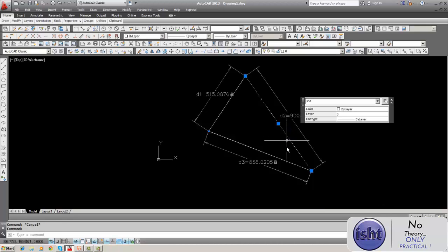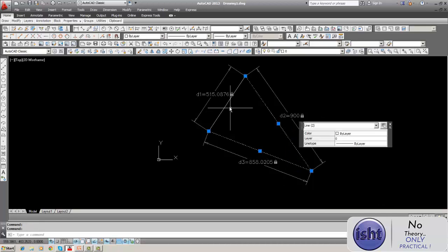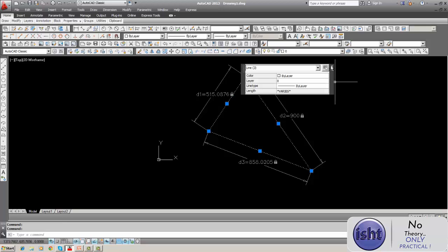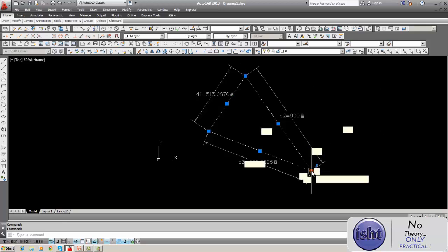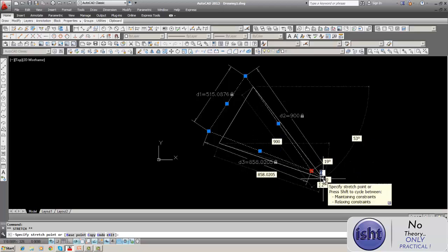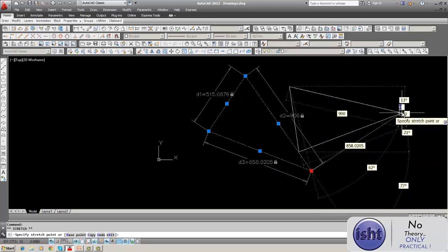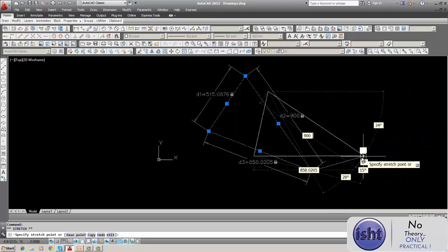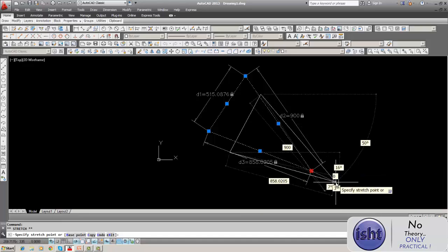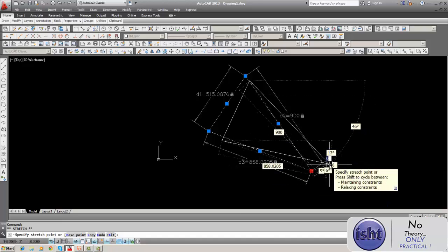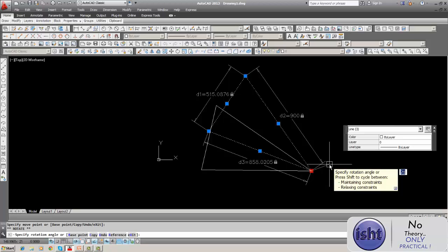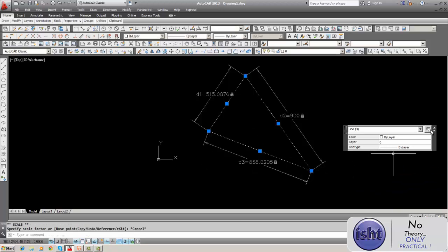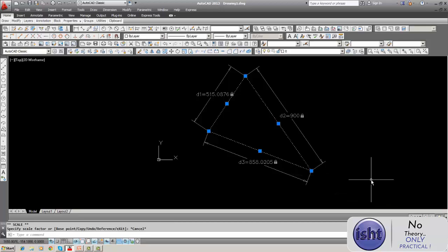Okay. Suppose I drag this line. So we will drag now. What is going to happen? Let us see. See, the entire triangle moves. Dimensions remain the same, but the triangle either can move or rotate as a single object, like a single straight line. Okay, that is because these constraints should be the same. This fixed constraint we have applied at this point should remain the same. It cannot change its position.